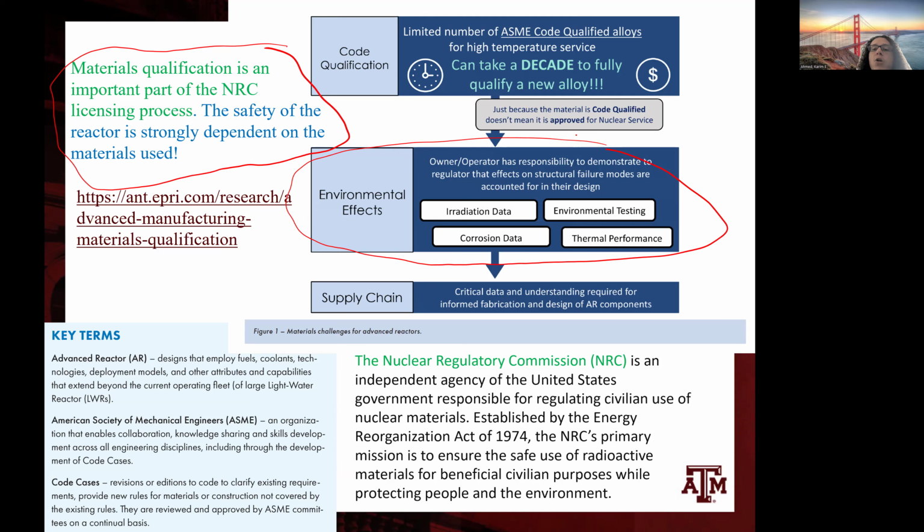Depending on the environment and the operating conditions of the reactor, whether it is a gas-cooled reactor or a molten salt reactor, it will be a combination of environmental effects and also radiation effects. So there have to be specialized testing and documentation of the material behavior under those conditions, and sometimes also under the coupled or synergistic effects.